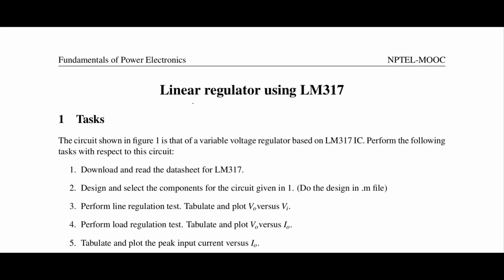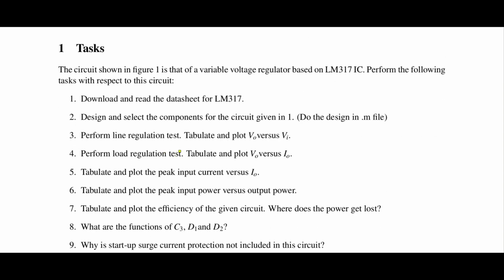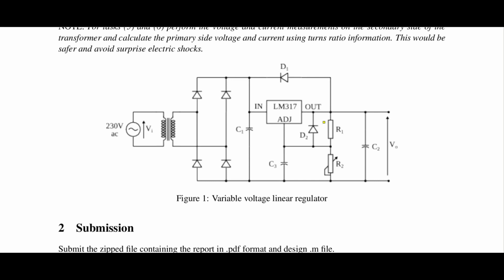There is another exercise that you can do, and that is linear regulator using LM317. So this is a IC regulator. It is a variable output voltage regulator. Download and read the data sheet, very important, and design and select the components using a .m file in Octave or MATLAB.